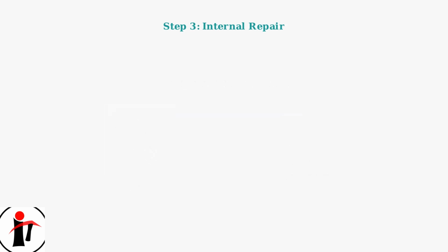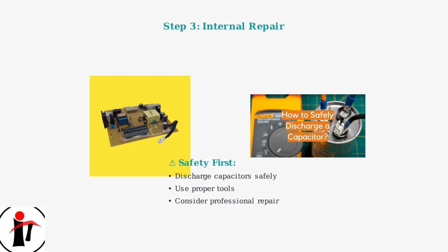The 1000 microfarad 25-volt capacitor and the 470 microfarad 16-volt capacitors are the primary culprits in most Sceptre monitor restart issues. When working with capacitors, safety is crucial. Always discharge capacitors properly before handling them. If you're not comfortable with electronics repair, consider professional service or power supply board replacement.